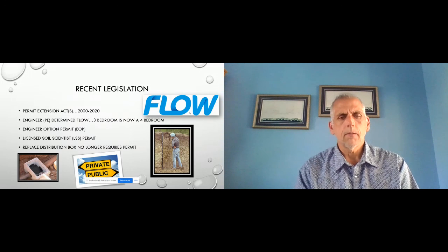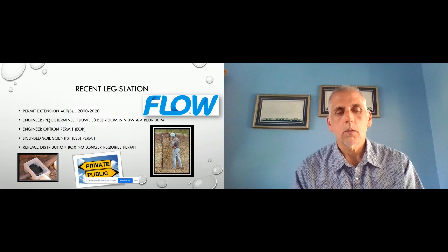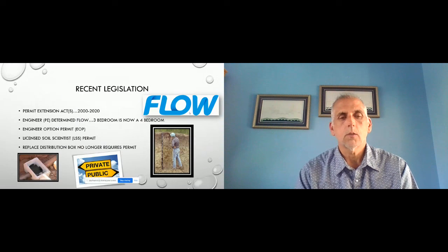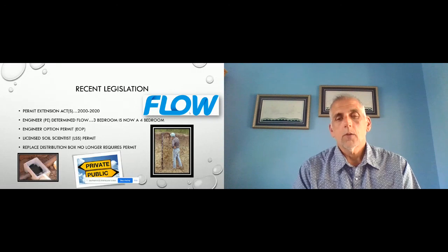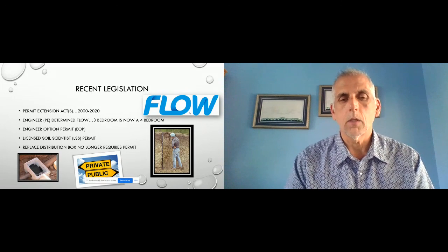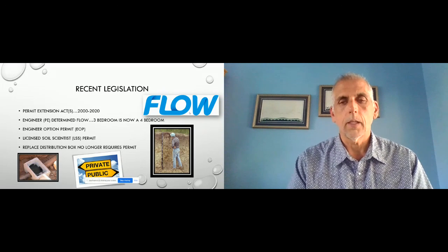That's called a 114. Another thing that's happened is that contractors now can replace D-boxes without a permit. So without coming to the health department at all, they can do a lot of work to a septic system and replace the D-box. That's not the septic tank. It's not the pressure manifold box. It is just the distribution box. So I've talked to a lot of contractors about this, and I told them that it's up to them, but if I were them, I would still request for the health department to come out and at least make a field note and a document to the file that it was done, and it was done correctly.